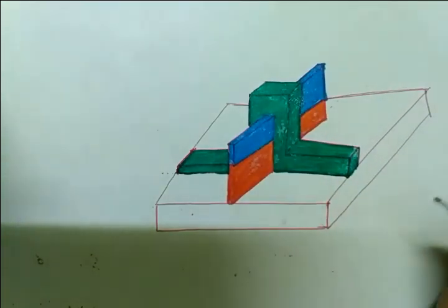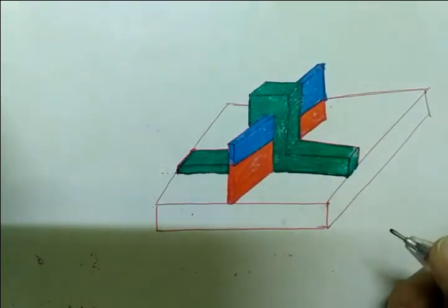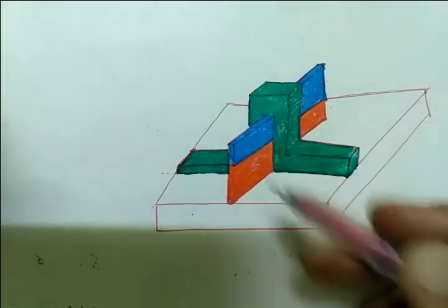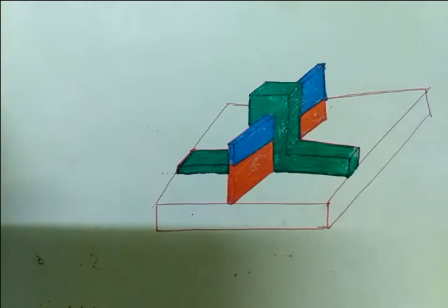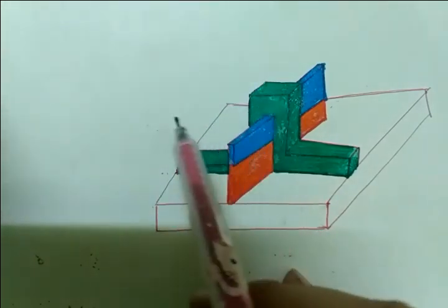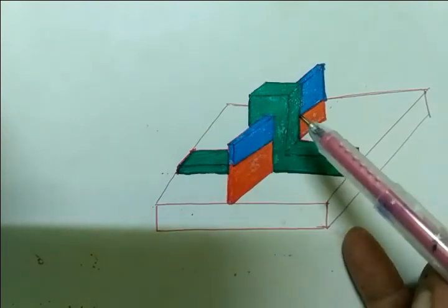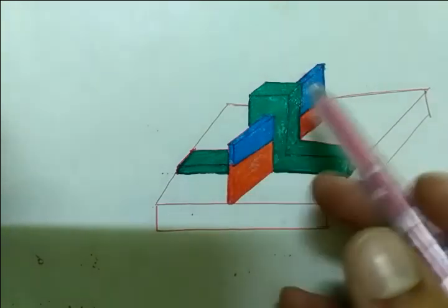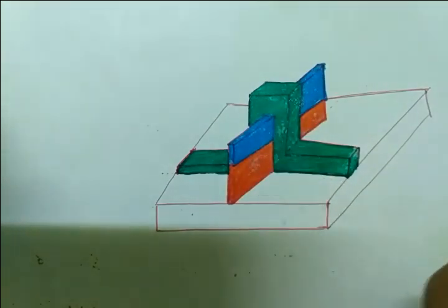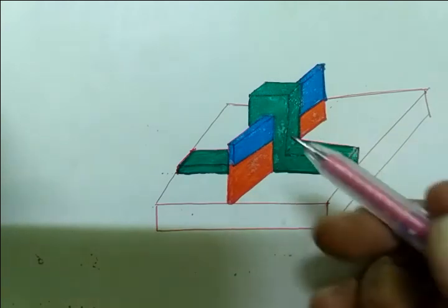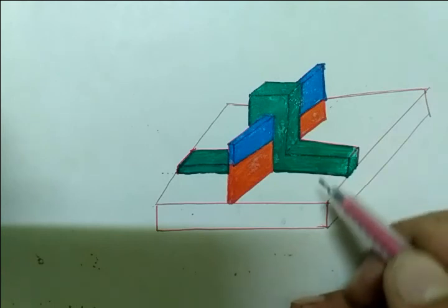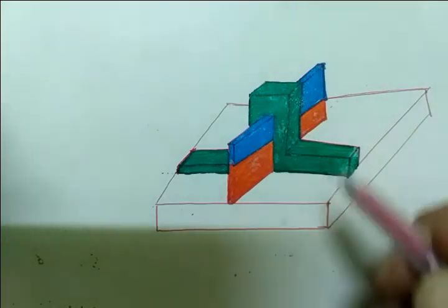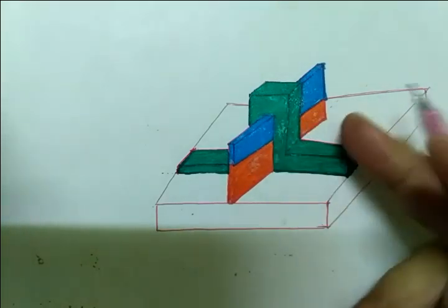As I have already said, it is often called an SOI device, which means silicon on insulator device. So from this structure, it is very clear. And lastly, the channel connecting the source and drain regions is usually called the fin. The fin parameters, like fin height and fin thickness, play a key role in the operational characteristics of the device.